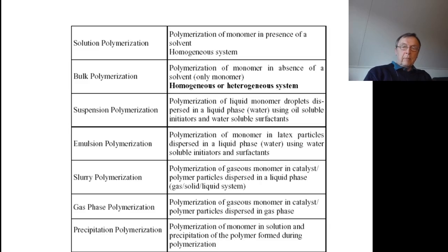The most advanced method looks to be the simplest, but it is not. It's a sophisticated method. It's a gas phase polymerization that converts monomers from the gas phase directly into solid polymers without the application of any solvent. So, if you use no solvent in the process, you don't have to remove it in the end.